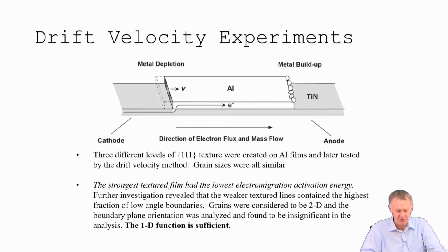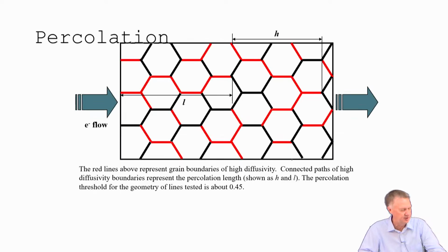I should have put this first about what happens, but this is how you measure the misorientation or the time to failure. Now there's another parameter that's important, and we don't get this in looking at our misorientation angle histogram, and we don't get it at looking at the misorientation distribution function. And we don't even get it in looking at the function that has the misorientation and the boundary plane. 5 dimensions, 8 dimensions of data, we still don't get any type of information on how things are connected.